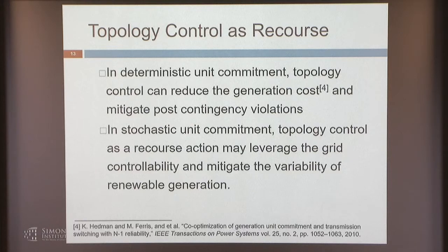So the idea is that we formulate the problem as a two-stage stochastic program. Two-stage stochastic programming is actually an idealized version of what currently is being done in the market. The different ISOs essentially do a market implementation of two-stage stochastic programming by having a two-settlement system, where you have a day-ahead market and then a real-time market. The people in the day-ahead market submit bids anticipating the uncertainty.